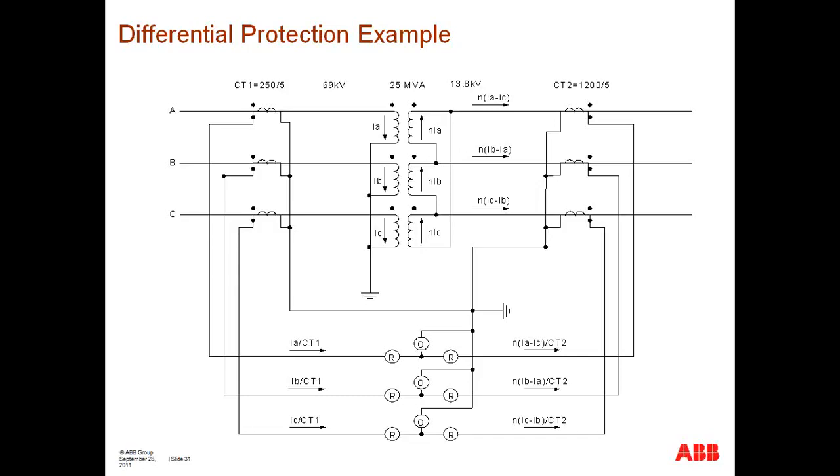Let's explore the principle of how it works. It's essentially monitoring a rapid rise of pressure inside of the transformer. That rapid rise of pressure is usually going to be the result of oil breaking down inside of the tank, which in turn decomposes into gas, which in turn raises the pressure inside of the tank. That sequence of events can only occur if arcing occurs inside of the tank of the transformer, thus indicating that an internal fault exists.